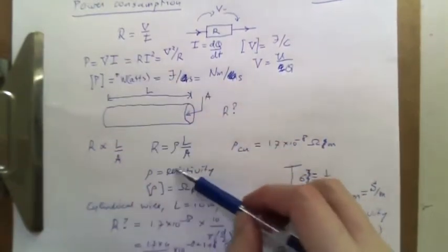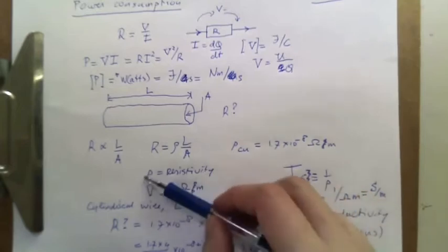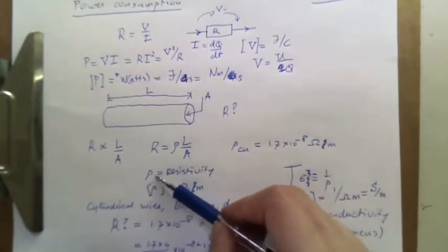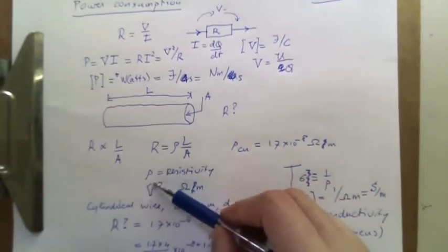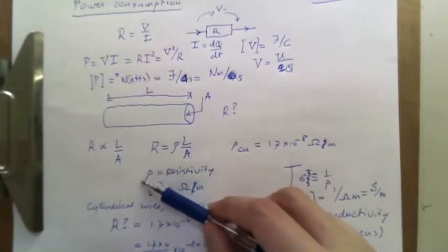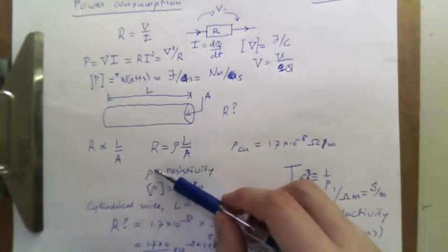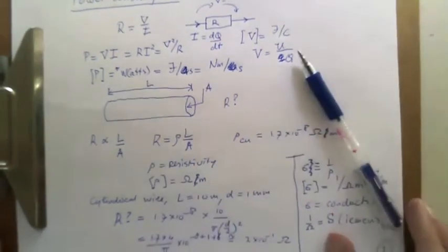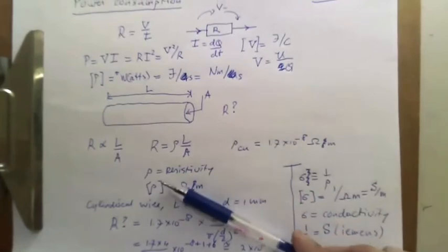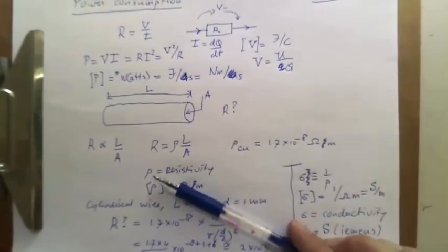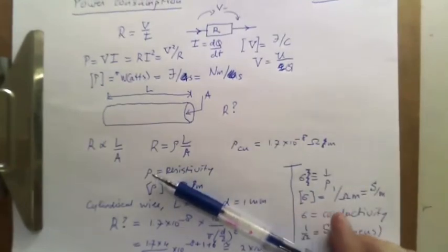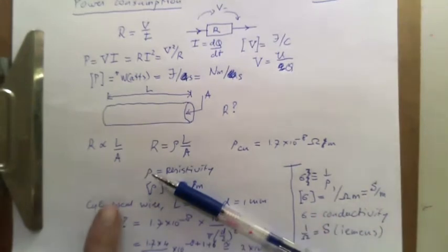Now we know how to quantify the resistance because we have this number, resistivity, but underneath this material quantity, there's a whole bunch of stuff. So when electrons move through materials, they can scatter off impurities, they can scatter off of lattice vibrations. There could be bends and nicks. There could be grains that make poor contact. So the study of what this resistivity is is an entire field unto itself. And there are temperature dependencies.